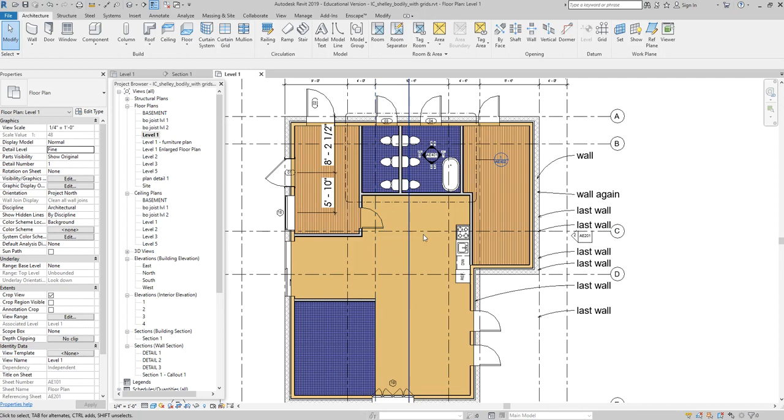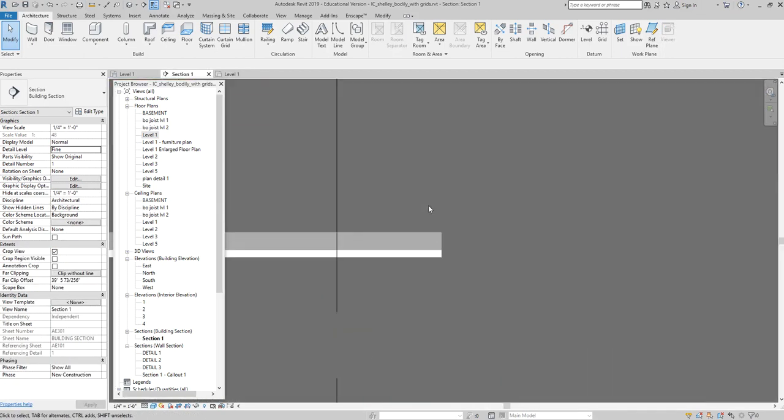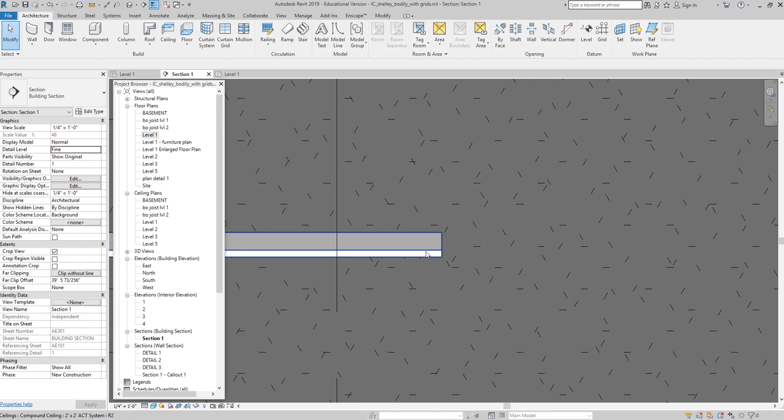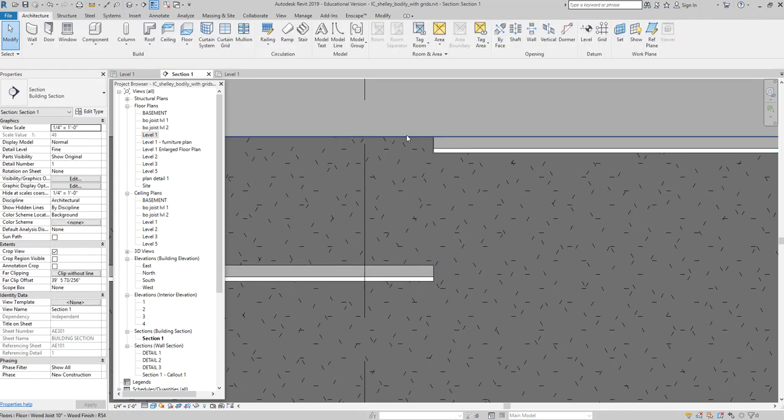All right. And so what I have to do here is place a wall in my floor plan, level 1, and give it a base offset so that it doesn't go to the floor, but it starts where I want it to start. Let's say we want it to start right here. That's lay-in. This is going to be wonky. We're going to put a gypsum board soffit right there, but we'll just have it come down to here. We want it to go from here all the way up and fill that gap, right? So our stud wall and our gypsum board is just going to live right in that nice little space, okay?